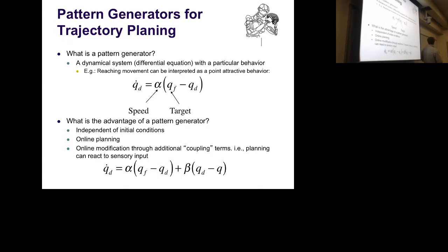So what's gonna happen if I were not using this additional term, but just this term? Well, the plan would just be continuing. So the black plan is completely decoupled from reality at this moment. Okay? Cannot react. If I add this term, it's now actually looking at the error between the desired and Q, which becomes bigger and bigger.